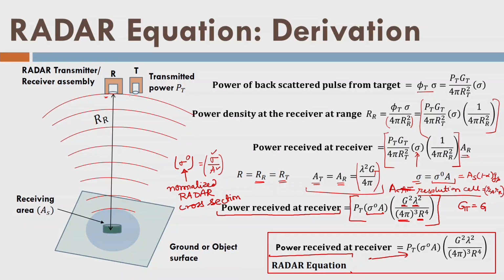Now, if this power is more than 50% of the transmitted one, then I will accept it as a backscatter. Otherwise, I reject it, saying that there could not be any object, or the object is so far away that we are not interested to measure it. This equation of the radar is similar to the LIDAR equation, but the terminologies are quite different, and that is why we have included it here.